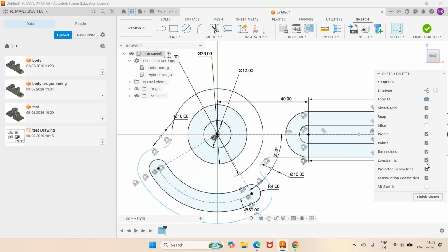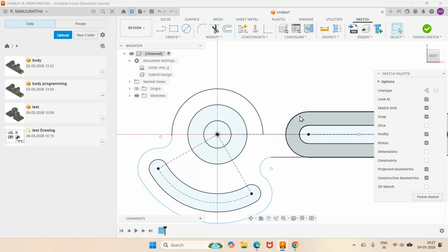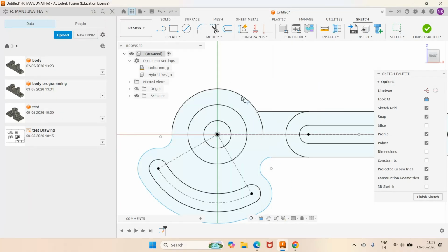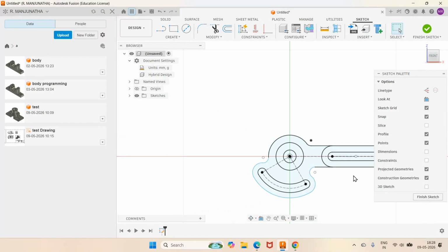Now the next thing is I want to take this line forward now. I will go for line, select this point on this side. Or can we extend this? Let us say I will go for extend, select this line. Then once you get this, similarly, I want to go for radius 5. Go to fillet, select on this side and on this side, the radius is 5. Enter. Okay. So we have this entire profile has been constructed.